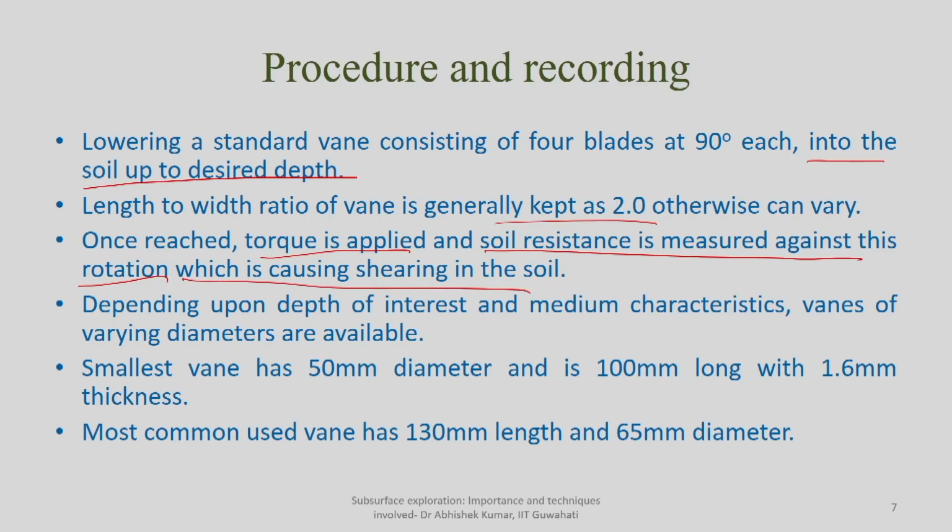Remember, when you go for the vane shear test, you are inducing shear forces by means of torque or rotation, and the resistance offered will give you an indication of the in situ shear strength of the material. Depending upon the depth of interest and medium characteristics, vanes of varying diameter are available.